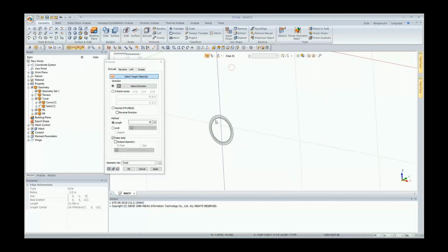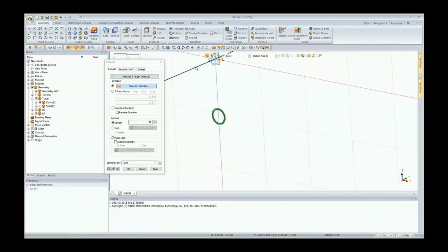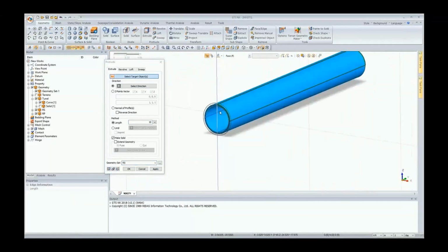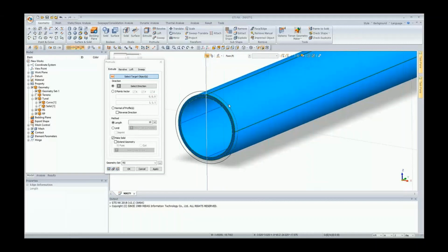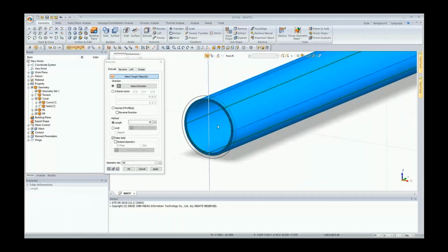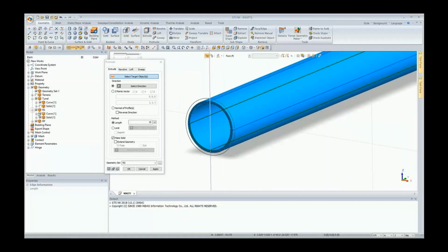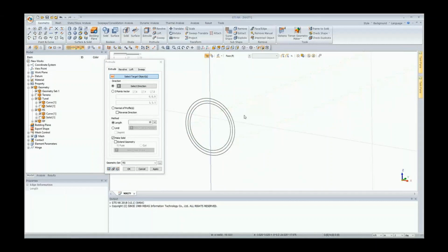So I click both of these circles now, the outer and the bottom boundary. The direction will be the same in the y direction. And I'll do this again for 45 meters. And this is now under secondary support, as I'm putting here, RS. Then we can verify here now this new solid created. So I hide this one more time, and I repeat this for the next edge.